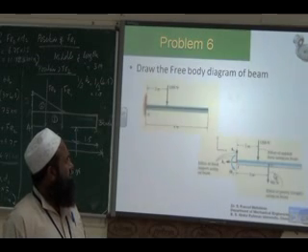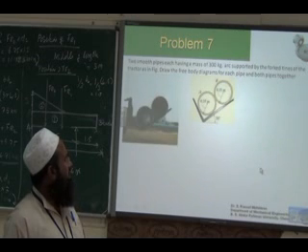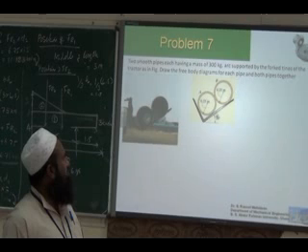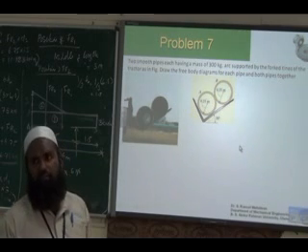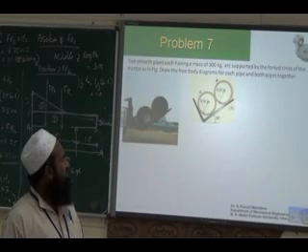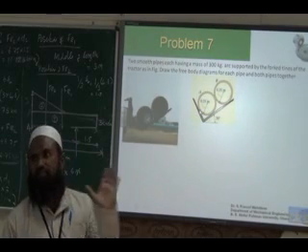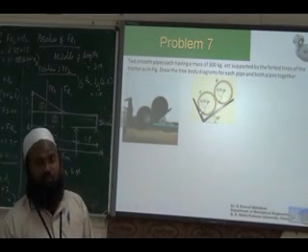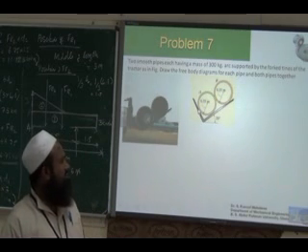Okay. So this is another case: a fork lifting crane is lifting two hollow roller pipes. So what kind of reaction will they have? The fork develops some restriction for the cylinders to move. So perpendicular to the contact surfaces, we will have reactive force.